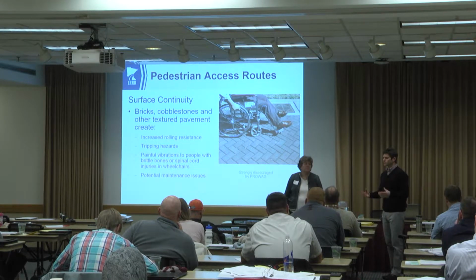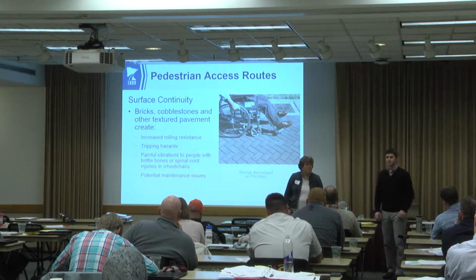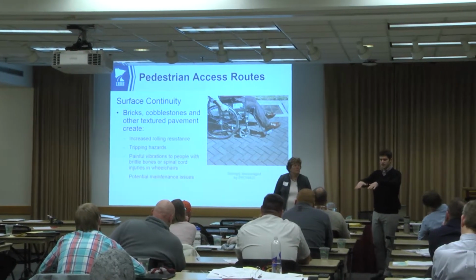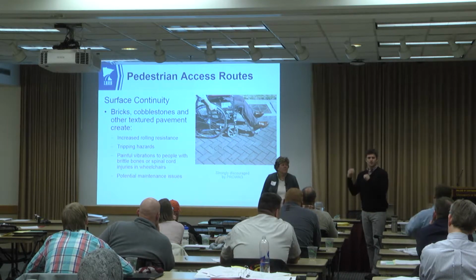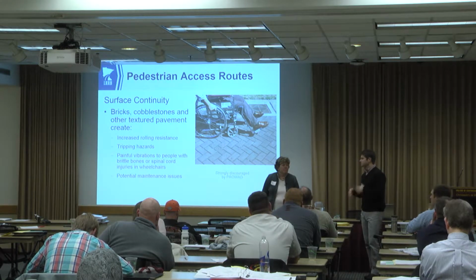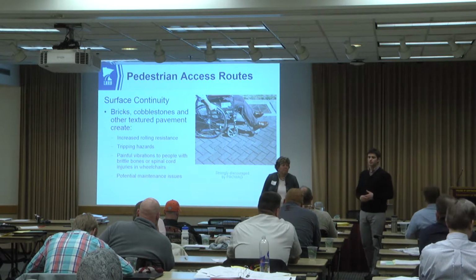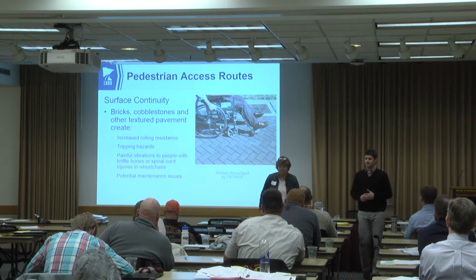We had a couple projects where we had pavers spread across the width, kind of a decorative band or so. Get them out. A lot of times you'd see them where maybe the ramp of the curb ramp is concrete, and then there's pavers on top. Well, technically that's in the landing. We're getting them out of the access route almost pretty consistently now. So for the time being, be aware that it's strongly discouraged, and we're probably getting to the point where they won't be allowed in the access route at all.